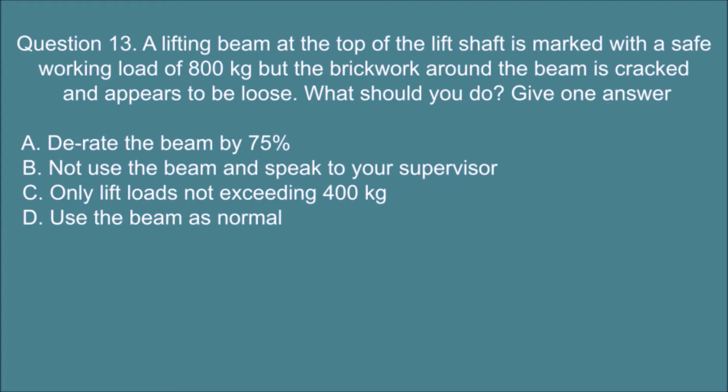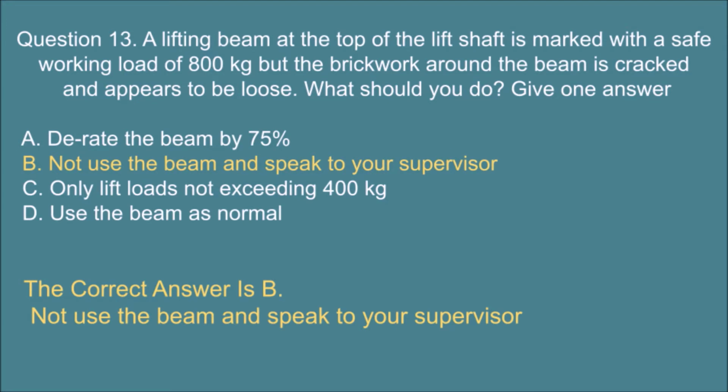What should you do? Give one answer. A. Derate the beam by 75%. B. Not use the beam and speak to your supervisor. C. Only lift loads not exceeding 400 kilograms. D. Use the beam as normal. The correct answer is B. Not use the beam and speak to your supervisor.